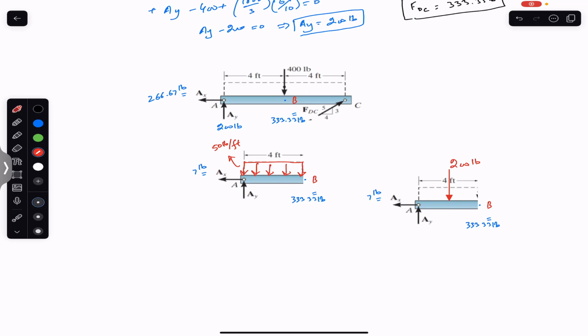So now we have represented that distributed load by its corresponding concentrated resultant. And now we have to represent the internal forces. So at B we will have the normal force, and we have to show the shear force. So the positive convention for the shear force on the right hand side of the segment is in the downward direction. So this will be my VB, the shear force at point B.